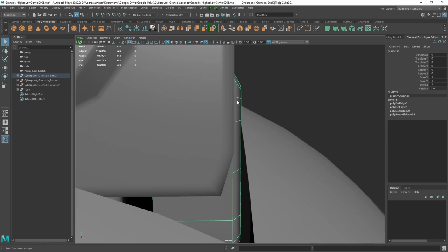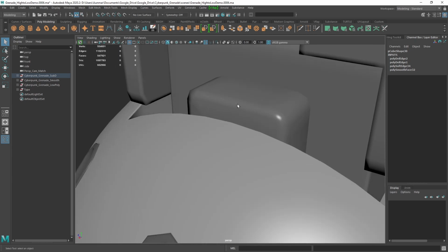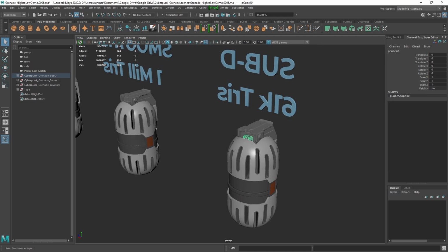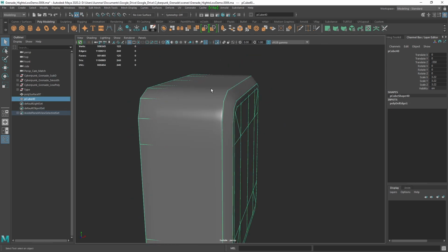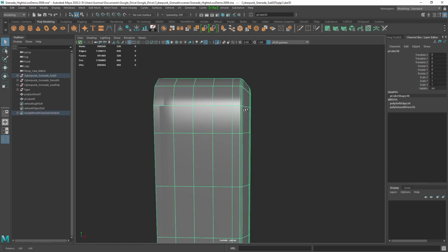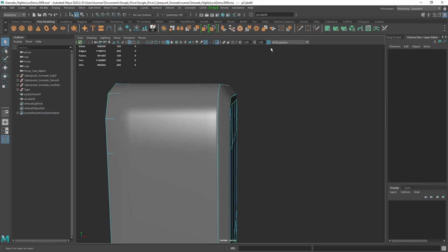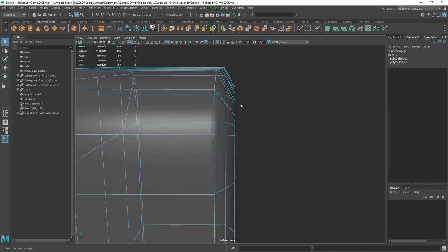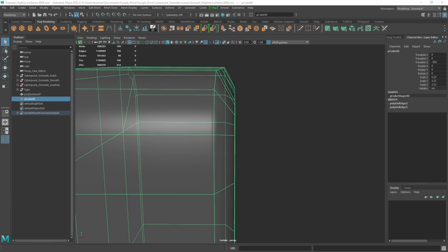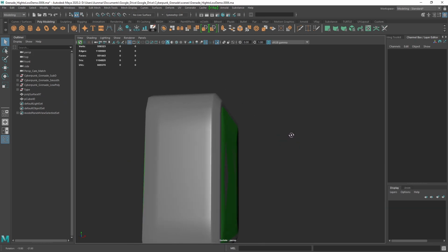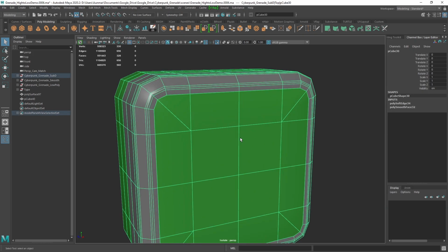And then you can see if I turn on the lights again and take a look at the original mesh, you can see what kind of problems that would cause. As you can see here, here's the optimized version, and then this is the high poly version. And you can see that if I were to take the low poly version now and remove this key edge here that's defining this silhouette, that's going to cause a lot of issues, and it's going to cause baking issues, right? You'll see that here if I go ahead and assign a different material to this, something like this, where we have the green here on the low poly, and then you can see the difference that's causing.